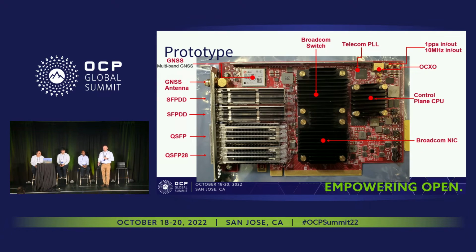One other challenge about the PCIe form factor is that PTM is a great solution, but there's really no way to export PPS or any kind of clocking information onto the connector. There's a bunch of proprietary stuff. So as a timing community, it would be really good if we could figure out a way to get timing information, like PPS, real clocks, onto that pinout. And I think as a community, if we pushed it, it may happen. But it's really a challenge until we broadly deploy PTM and get it to really work. Synchronizing multiple clocks, multiple cards, requires cables that go between them.